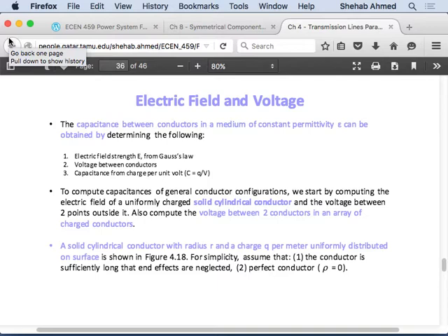And there you would have to consider, of course, the different line models and all the capacitances and inductances that you calculate around the system, because they would affect the transient response of the system, right? So here, this course is mainly concerned about the steady state performance of the power system. In the steady state performance, we will only consider the short time model because that's what gives you the power rating of equipment. That will not consider some of the transients that are in the system.